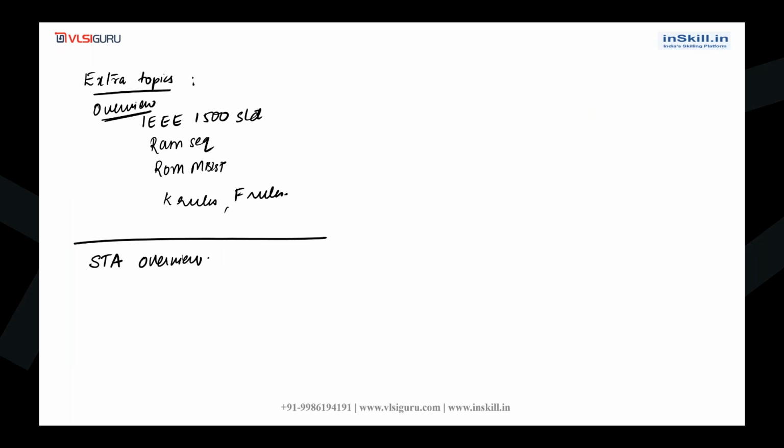I'll cover what is setup time, what is hold time, what is a setup violation, what is a hold violation, and problem-type questions, like if your interviewer gives a circuit and asks you to find the maximum frequency of operation, or whether there is any setup or hold violation in the circuit. Also what is latency, what is skew, what is jitter, what is uncertainty, what is removal time, what is recovery time. Such basics we'll cover in STA.